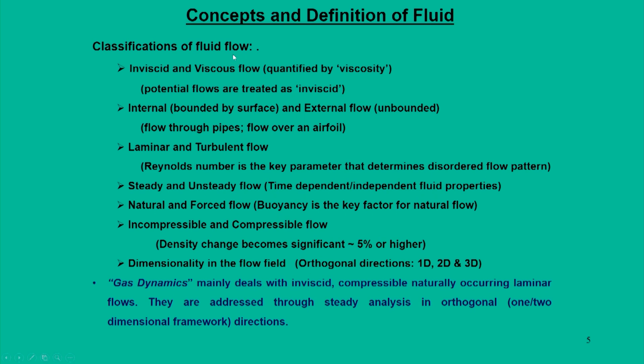When I am talking about these classifications, we are mostly talking about those which deal with gases that are compressible in nature. The second category of fluid flow is internal flow, which is bounded by a surface, so flow inside a duct, and external flow, which is unbounded, such as flow over an airfoil.